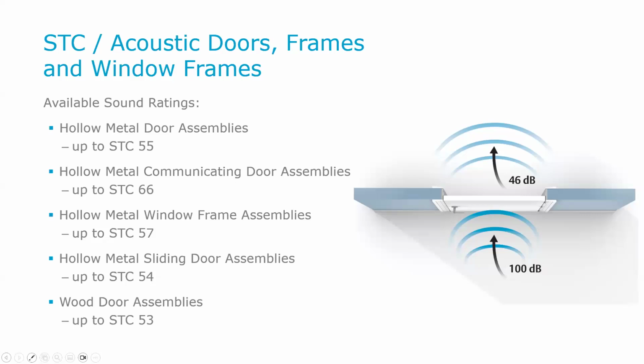And what cam lift hinges will do is, because of the weight of that door, you have to have hinges that will be able to open that door, lift it, and then as it swings and closes, it sits on the threshold. When you get over 50, standard types of hinges, whether they're heavyweight, 5-inch or whatever, won't be able to do the job. So you have to go to cam lift hinges, which are supplied by the manufacturer.